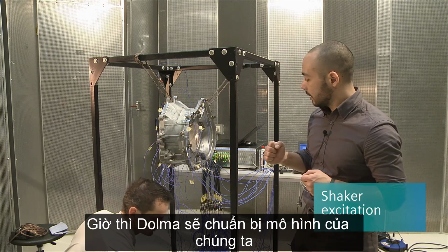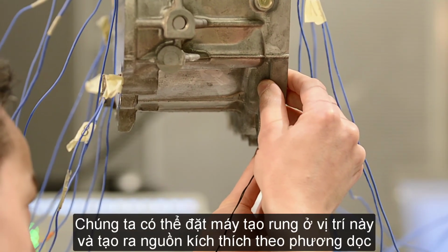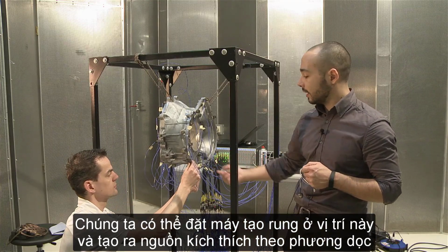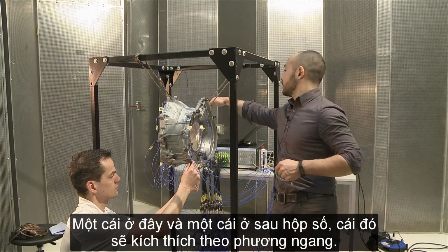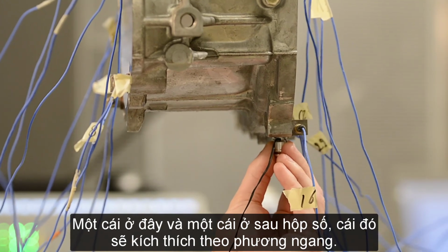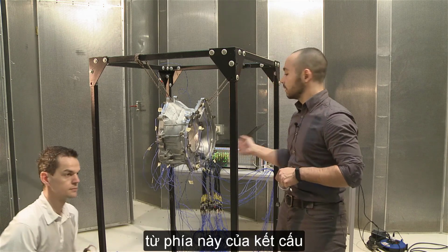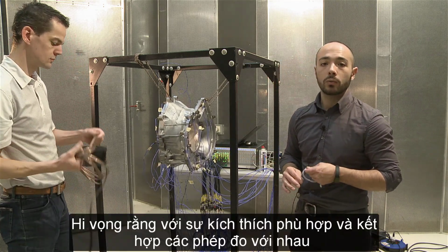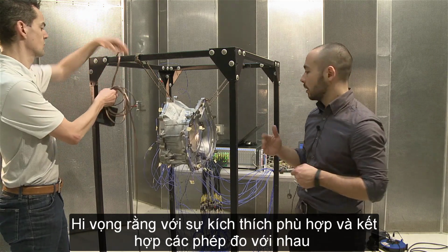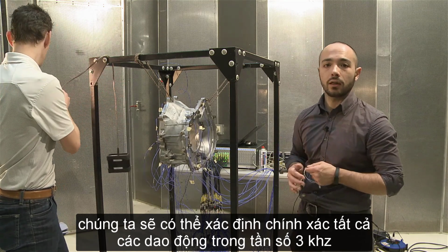Now, Tom is preparing the support where we can place the shaker, and we will perform 2 excitations in the vertical direction, one here and one basically on the back of the gearbox, and another one in the transverse direction, where we will excite from this side of the structure. So hopefully with the proper excitation and by combining the 3 measurements together, we should be able to correctly identify all the modes up to at least 3 kHz.